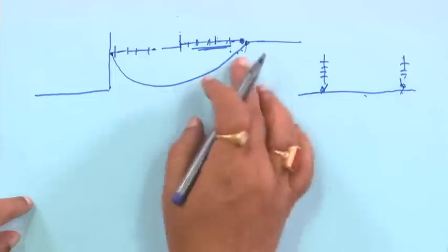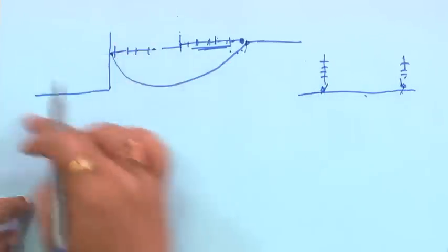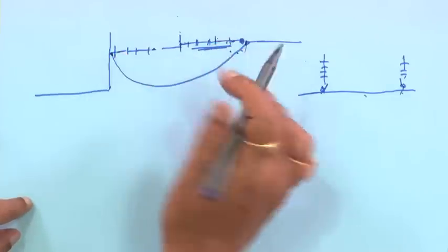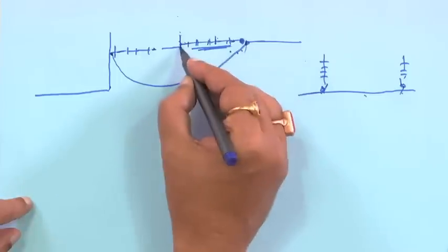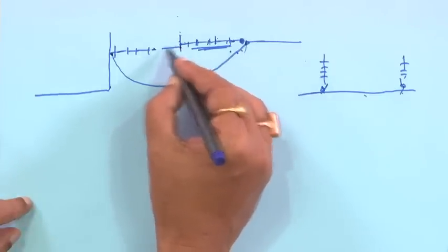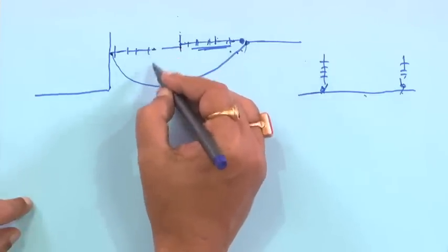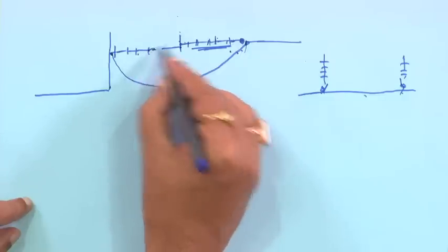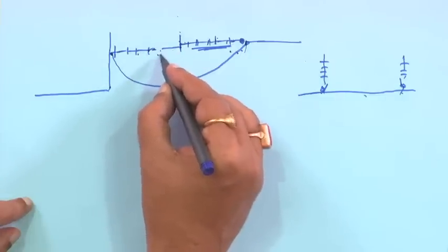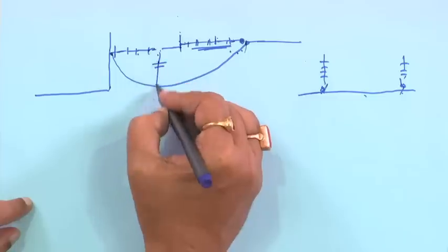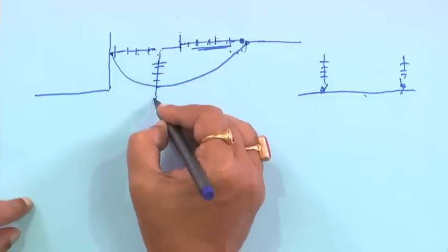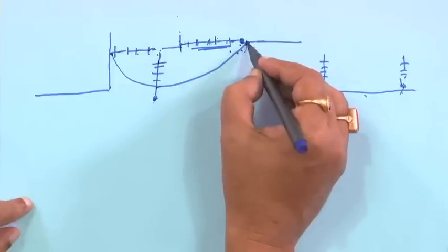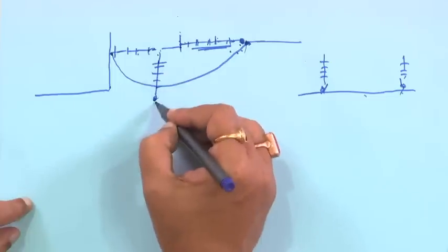But the question is, when the line is coming from somewhere and taking another direction, either side you can see a horizontal type, or sometimes you can see it coming like this, and after that from some other cross arm, maybe a string insulator is coming, something like this. From another cross arm I can make it like this. So many strings are there, and the conductor will go like this. In that case, this point and this point you have to connect, because this is a conductor end, and this is also a conductor.